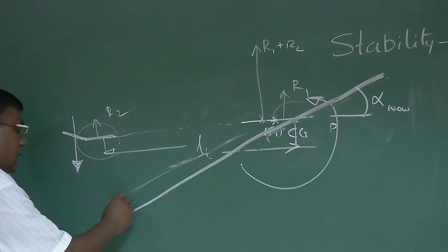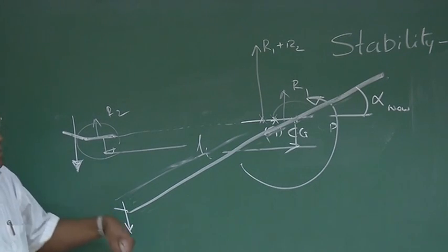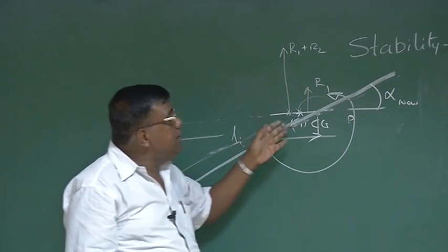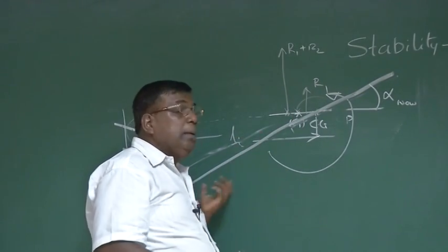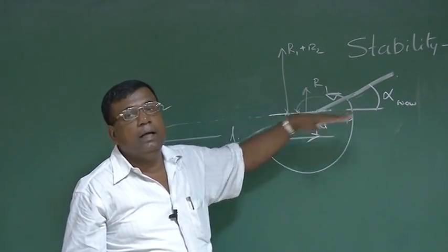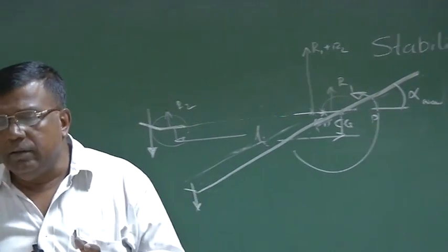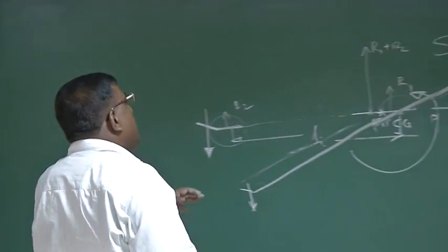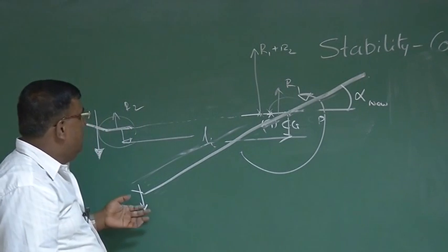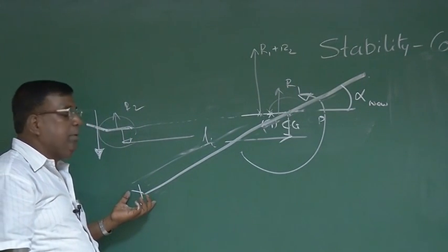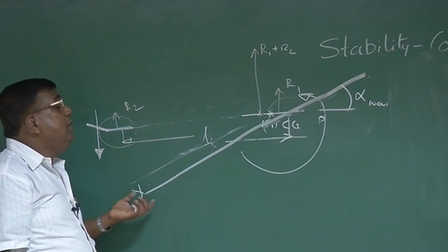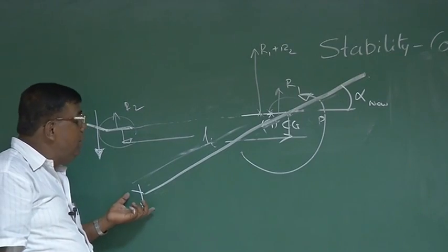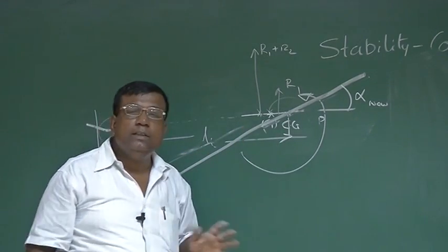And we are very clear that somehow we have to apply this moment through this force to hold this airplane, because otherwise, since it is statically stable, if we don't have this force, it will try to come back to original alpha. And this is, in a very holistic manner, the control problem. Okay? You can very well understand how much you can turn will also depend upon what is the force generating capability of this surface, or what is the moment generating capacity of this whole system. That will be decided by not only the force but also the moment arm. So these are a matter of details, right?